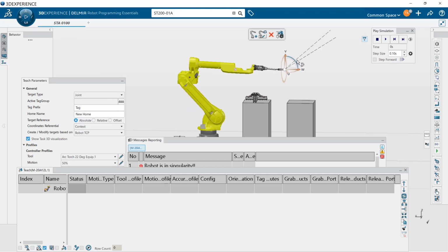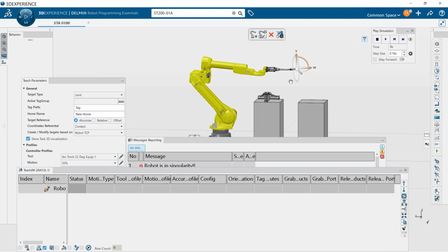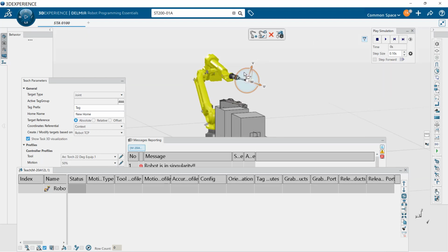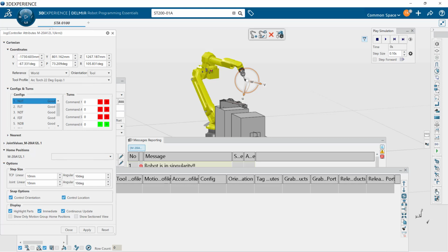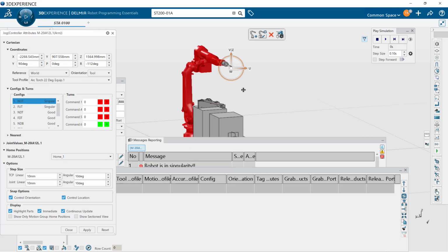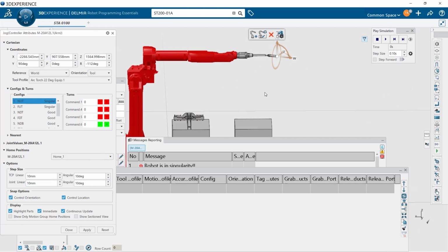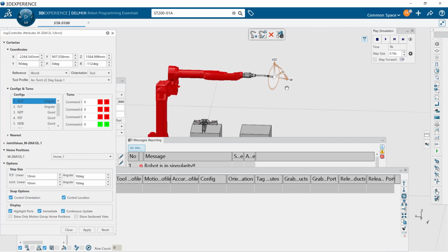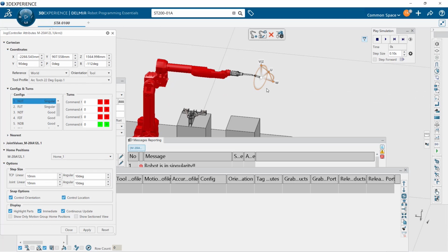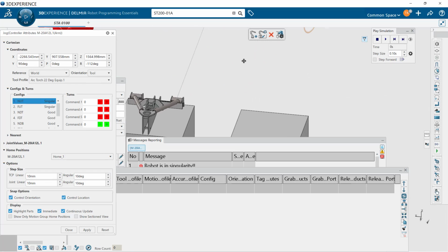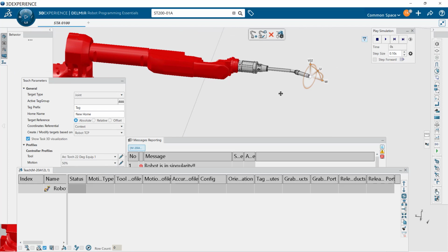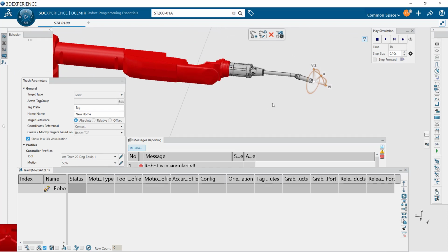And what it does is it tells us that the robot has multiple solutions for a position that you're trying to establish. It's ambiguous. And so when that happens, you get a warning that tells you that the robot's in singularity. So as a rule, when you're programming a robot, you should always stay away from singularity because the robot cannot calculate its way out of it because, again, the solutions are ambiguous and it can't compute. And when it does not compute, it is not a good thing.